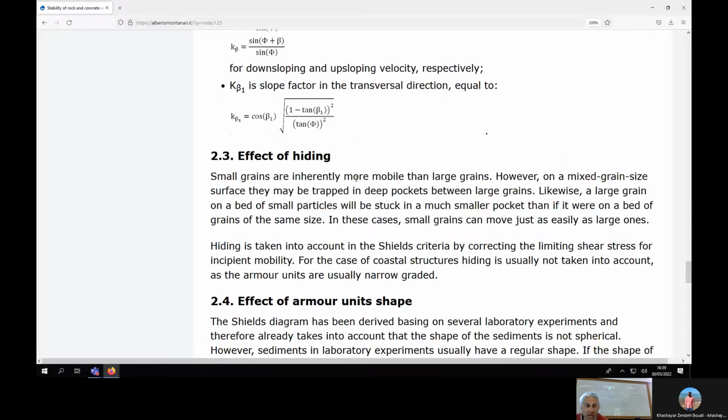Can I ask something? Yes. But the shear that we are using in order to develop these formulas is the surface shear of the wave or the current? No, it's the bottom shear stress. The bottom. Yeah. So if you have, before breaking, the shear stress at the bottom is almost zero. If you are in deep ocean, you have anyway an orbital movement of the particles.